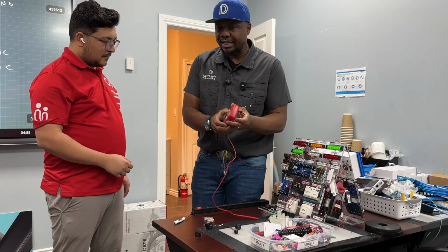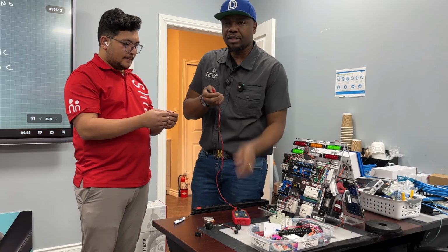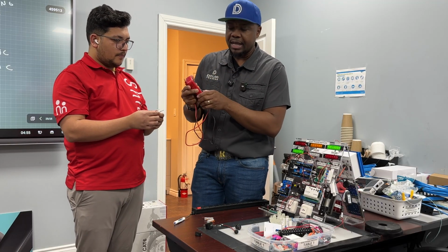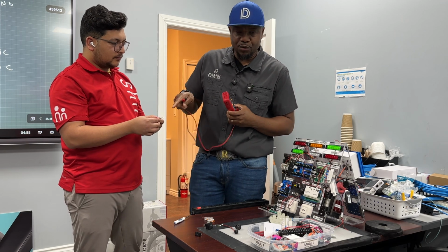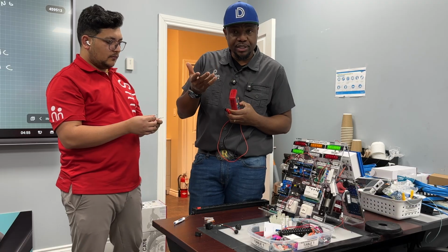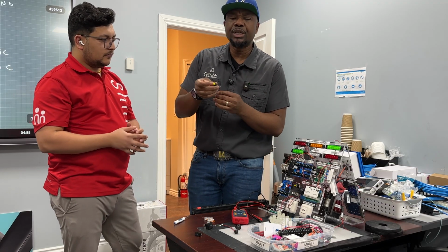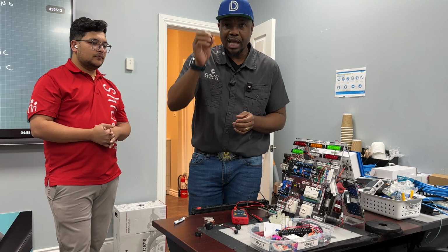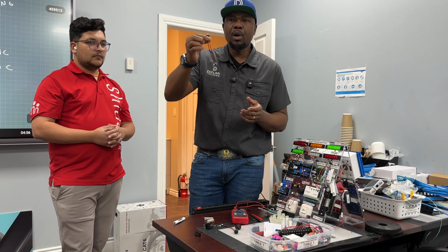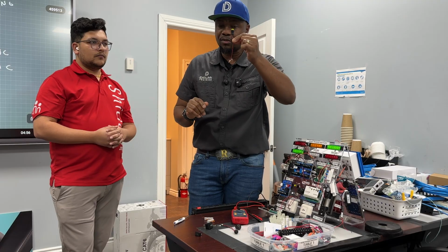So we have this on the continuity. So you're going to hold these two for me. And first of all, to start, I have to put this on the ohms. And the ohms, remember, there is no electricity flowing through here. I want to determine whether this switch is an open switch or it's a closed switch. In most of the times, they might tell you use a form A switch. So it's up to you to determine whether this is a form A switch or a form B switch. Always look at it in the default state. This is the default state that it comes from the factory.